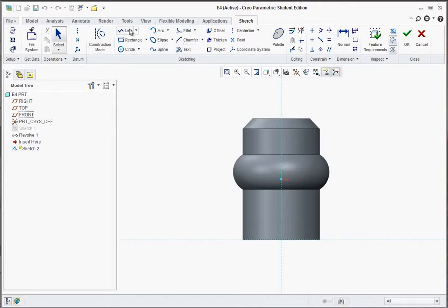Take your line tool, slide up to the middle here, and snap to that line in the center somewhere. But it doesn't have to be dead center. You're not going to find the dead center of the dome, just of the vertical center line that you see there. Click, drag out a horizontal line, click, and middle click a couple times. Double click on that and type in 2. And then this dimension should appear.